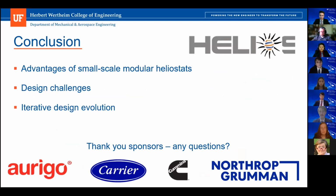Smaller scale also decreases the wind stresses on the modules due to the smaller footprint, and additionally, the materials chosen do not need to be as strong compared to large-scale heliostats because the forces are much smaller. Our off-the-shelf parts are durable enough to resist the forces in the field, and this allows us to decrease the cost by utilizing plastic parts and by reducing the amount of required manufacturing.